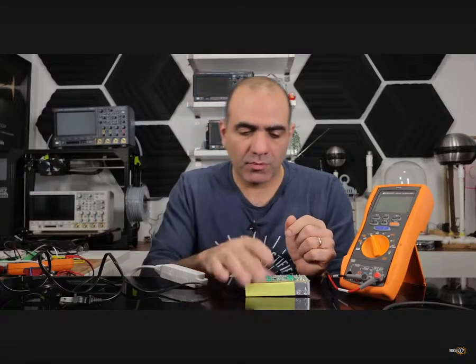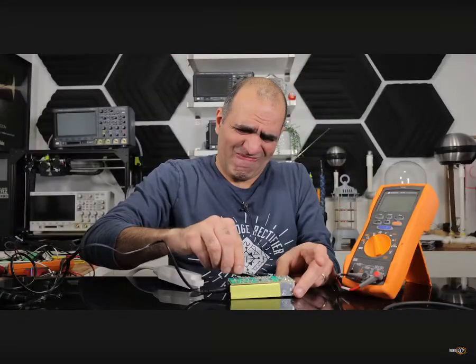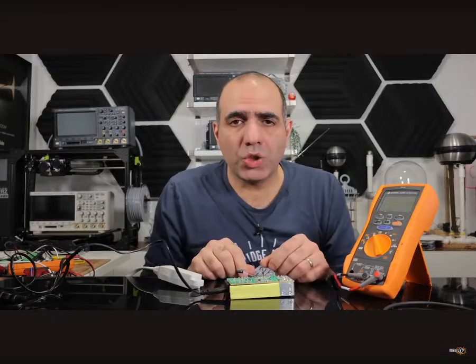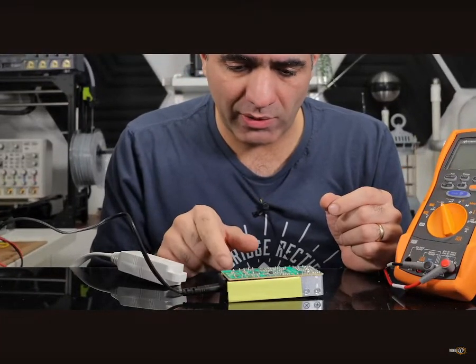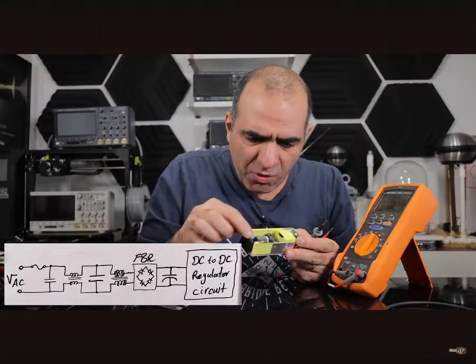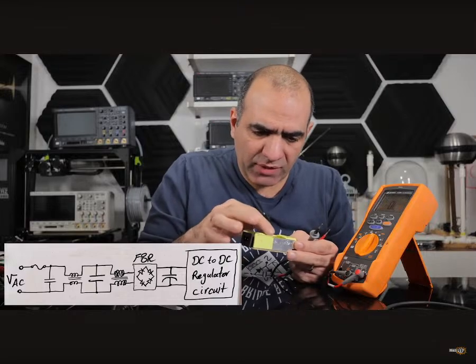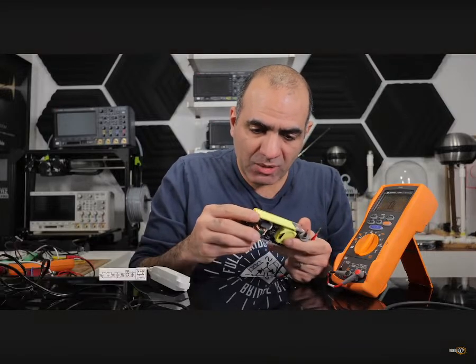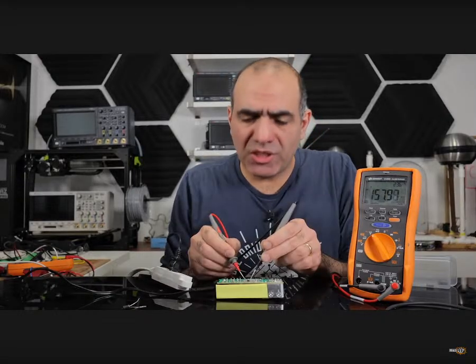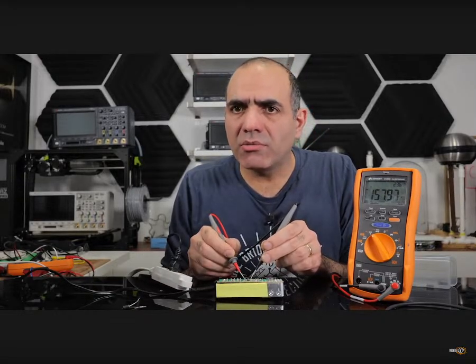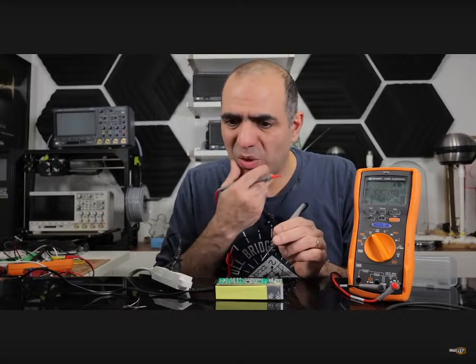Always disconnect power before touching a circuit. Always make sure the circuit's high voltage capacitors are discharged before touching the circuit. Just weld it. Okay, so there are a few input filter components, the rectifier and its capacitor. Let's measure the voltages. Around 115 volt AC input, around 160 volt rectified DC. So all seems good there. Must be the controller circuit.